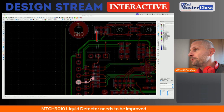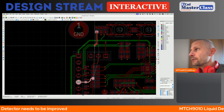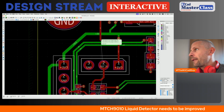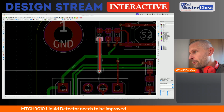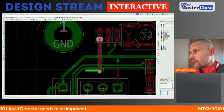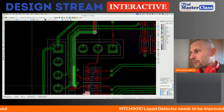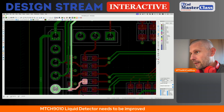And the wake up. I will place the via here and connect the third bottom layer track for the wake up. Exactly like this.